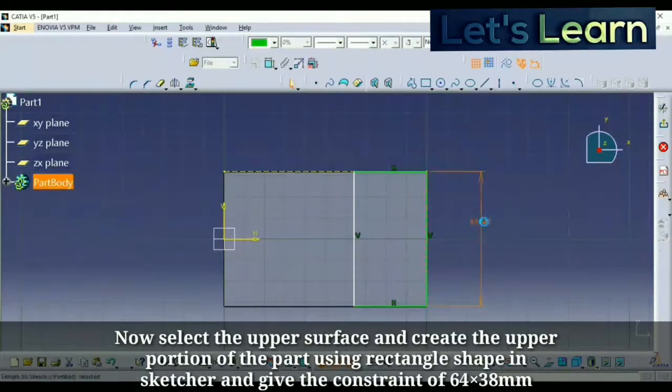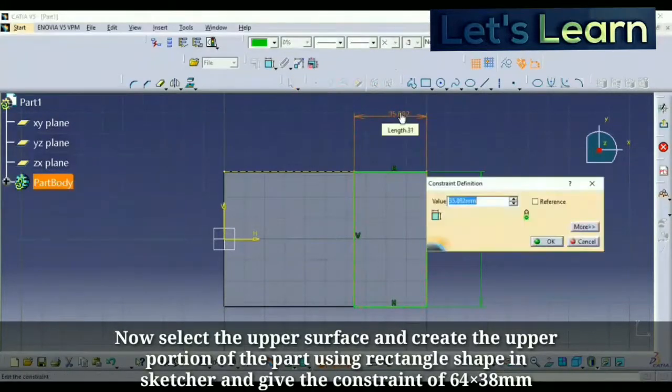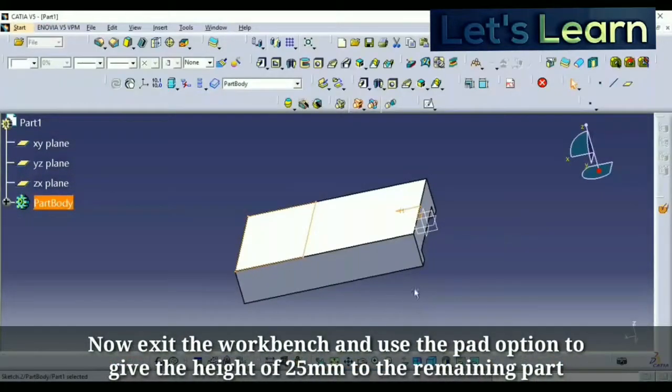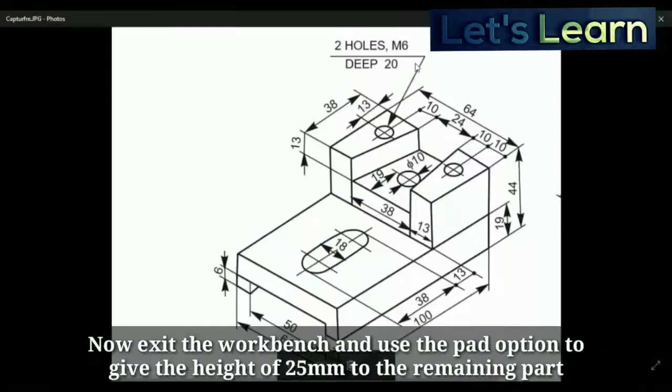So the height is 64 mm and the length is 38 mm, and then click on exit workbench, and now you can pad the component using the pad option. Click on that and give the dimension. You have to give it up to 44 minus 19. So you have to pad it accordingly.